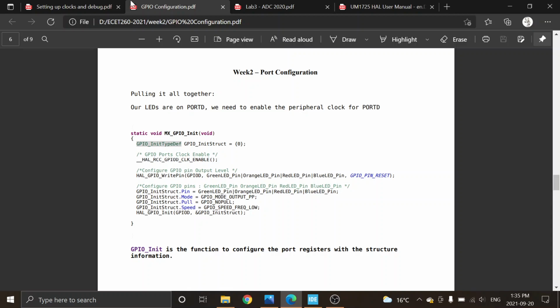There are also a few other things you'll see. There's a CMSIS layer, which the HAL API calls. There's also a bunch of drivers called LL, low-level drivers. Because of the layers of abstraction, there's a bunch more layers of software to get through, so it could be slower. The low-level drivers offer you the ability to speed things up by going more directly. It's like when Windows first came out, you couldn't play games on it because there were too many software layers. So Microsoft came up with DirectX, which goes through fewer of the layers and talks more directly to the hardware. It's the same kind of idea.